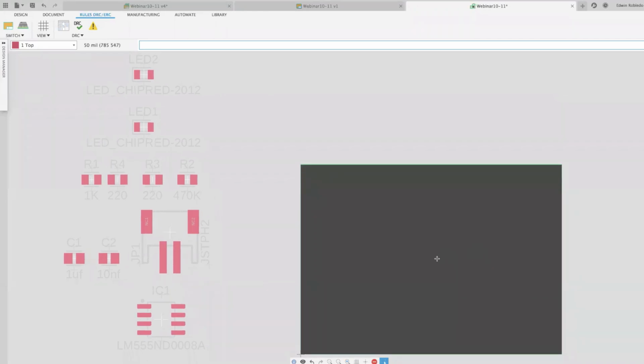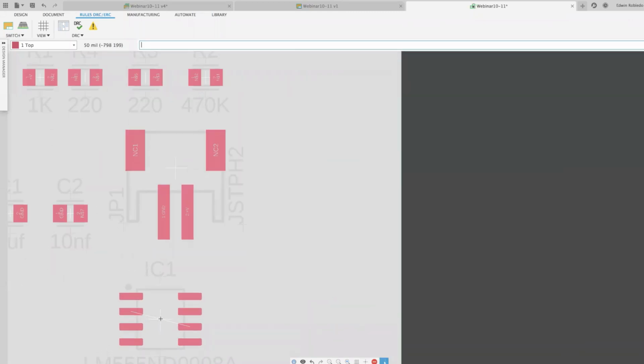Now I'm going to start selecting components and putting them inside the board outline. As you can see, the inside of the board has a slightly different color than the document outline as well. So this is my circuit board area. Since the default command is always group, I can click and hold on the origin or the handle of the component and select it. Well, in this case, I actually have a trace there. It's in my way, so it's not letting me grab it.